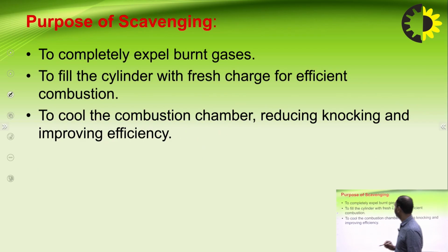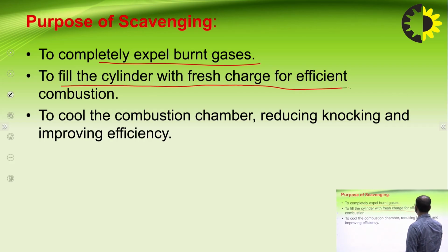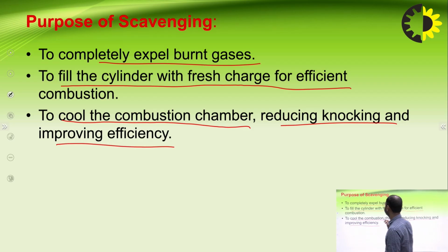Then what is the purpose of scavenging? Basically, to completely expel burnt gases, to fill the cylinder with fresh charge for efficient combustion, to cool the combustion chamber, reducing knocking and improving efficiency. So these are the purposes of scavenging.